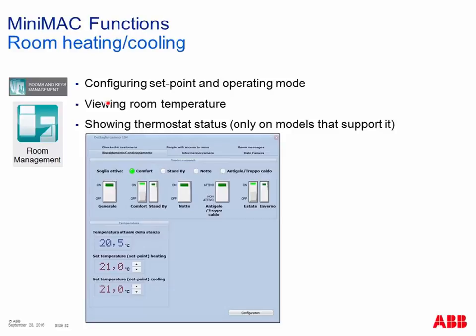But in big hotels, for sure, when you want to manage hundreds of rooms, but not only, also for medium hotels, usually a dedicated KNX supervision is needed, and MiniMAC is not able to do this. MiniMAC is only the supervision software and the commissioning software for access control. It can offer, as we are seeing now, an additional functionality, for example here for the heating and cooling, but it's not a KNX supervision software like, for example, Netx, Saia Burgess, Bactec, or so on.